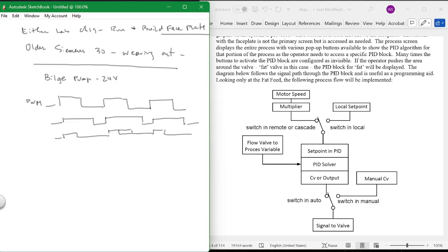Another case in point, this will be my last. A valve is turning to control the flow of gas into a furnace. There's a linkage between the motor that does the turning and the actual valve, and that linkage is mechanical. If a linkage comes loose, what happens? You turn, but it doesn't respond.